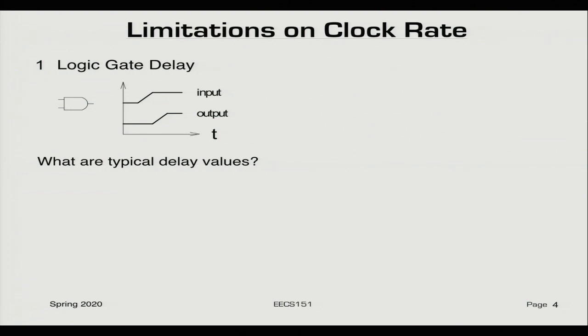And you would think, what has to happen within 1 clock period in a microprocessor? Well, you're going to go through a few logic gates at least. Every operation, you can do an addition in 1 clock period. We've looked at ripple adders. Even if we built a fancy adder, you're going to have to go through some number of logic gates, usually like the log of the number of inputs into your adder, but roughly. So probably 6 or 10 logic gates in series in 1 clock period.